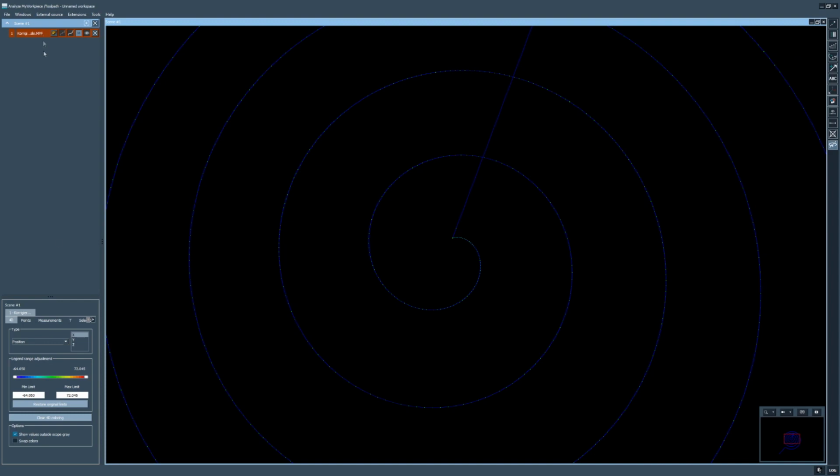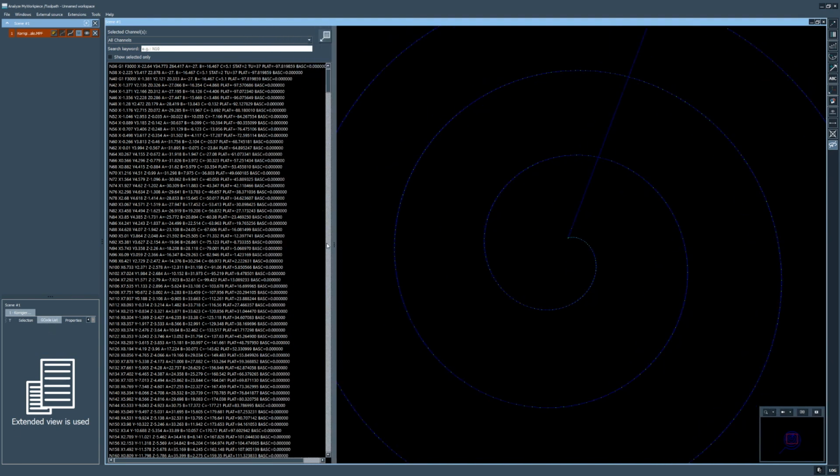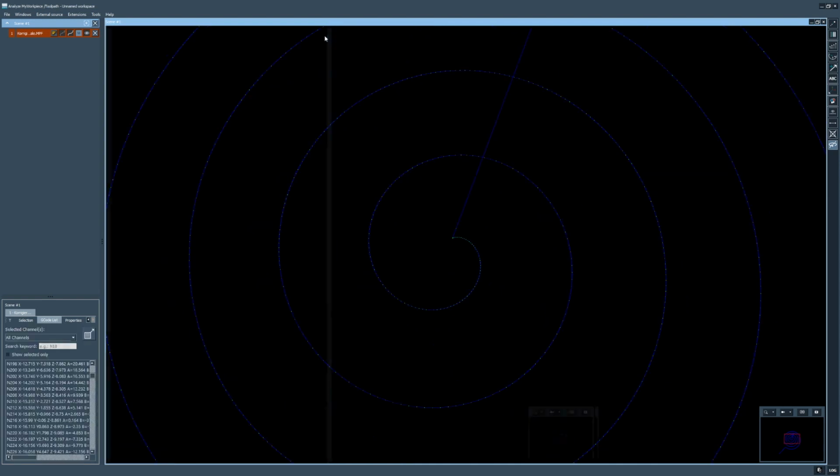In this MPF file which we have here, let's just check the code, and we will talk about this area here later. Going to the G-code list, we can see the G-code of this MPF file, and we see that it does not only contain the X, Y, Z information, but also A, B, C. That means that Toolpath understands how the toolpath is actually oriented.